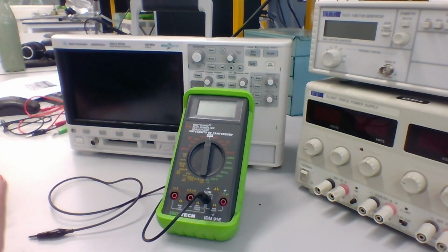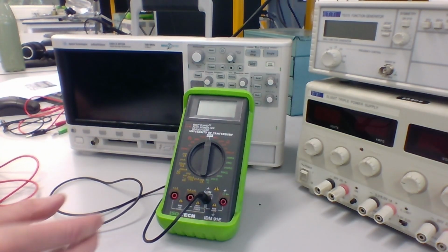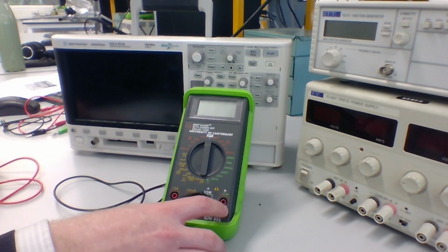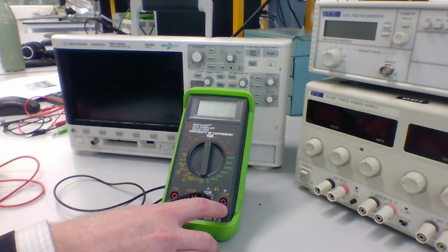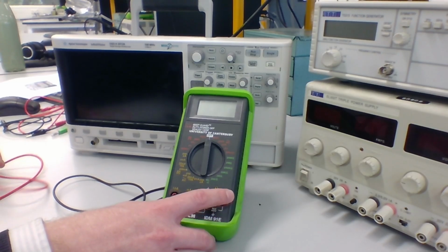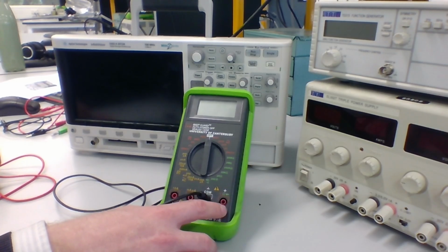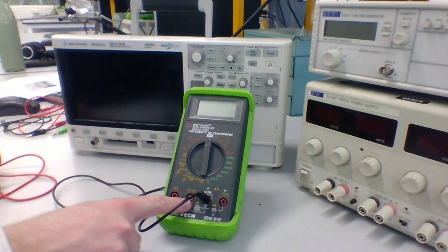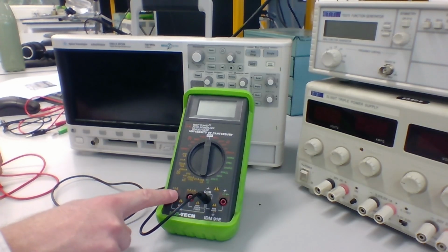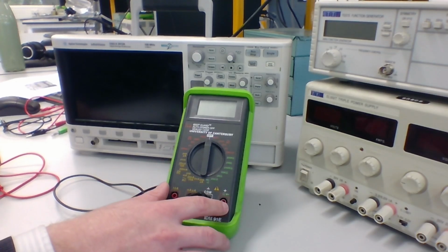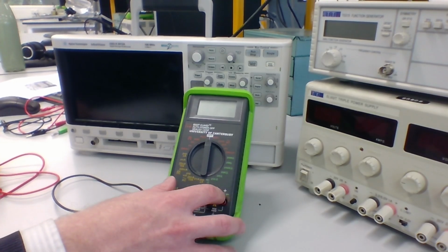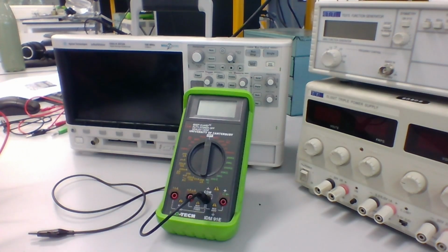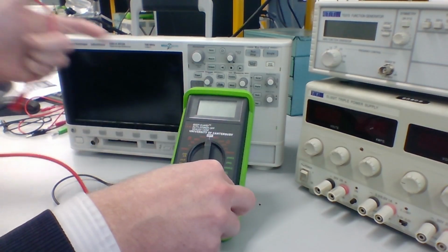To measure voltage, resistance, or to test a diode, we use the right-hand side terminal on this multimeter here. Note that it may be in a different location on different multimeters, but it will always be labeled. These two left-hand ones here are labeled with current markings, indicating they're for measuring currents. The right-hand one here is labeled with voltage, resistance, and diode to indicate its properties as well. So we connect in another banana to alligator clip cable in there.